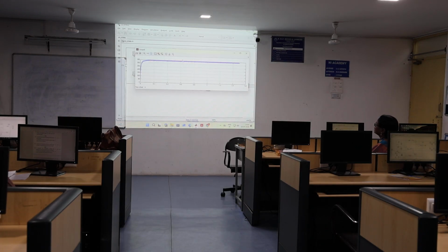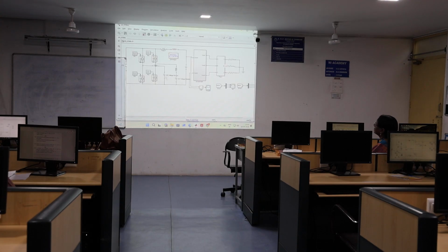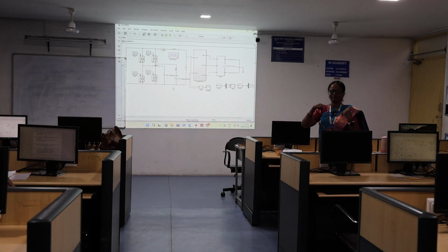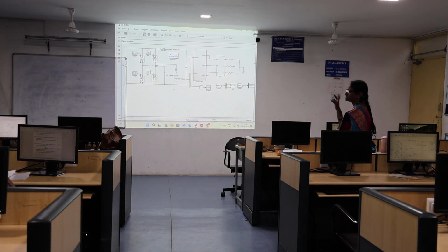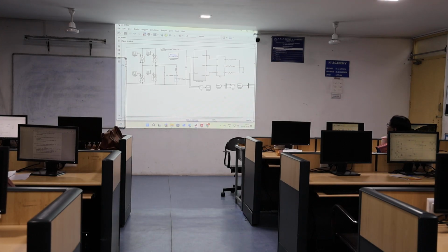So around 350 volt we were getting. Actually when you see that, my input voltage is 50 plus 50, 100, because in both the equations my voltages get added up. So (2 minus D) by (1 minus D), if I calculate, my value will be 3 when I put D equal to 0.5. So almost 50 plus 50, 100, 100 into 3, 300 volt, nearly we get that value.